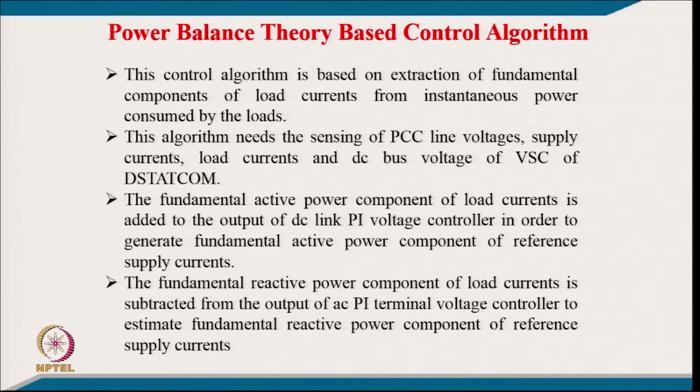Now, we will go to the second control algorithm. This is what we call the power balance theory based control algorithm, which I developed in 1996, and you will certainly find some literature related to that. This control algorithm is based on a very simple concept: extraction of the fundamental component of load current from the instantaneous power consumed by the load. Your load consumes active power, and this algorithm needs sensing of PCC line voltage, supply current, load current and DC link voltage of the VSC.